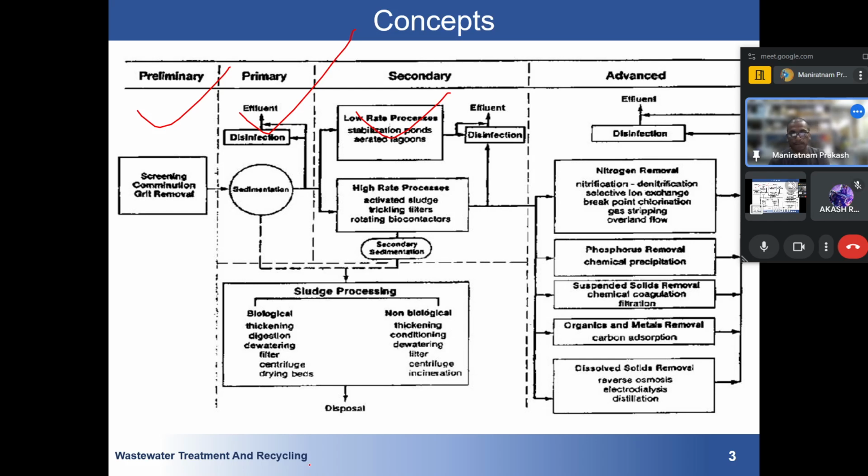There is also some discussion of sludge processing. In each process, whether it is primary or secondary treatment, we have sludge production. In the primary sedimentation tank, there was a mechanism at the bottom to collect the sludge, and this sludge has to be managed. In the next lecture we will discuss more about how this sludge is processed.